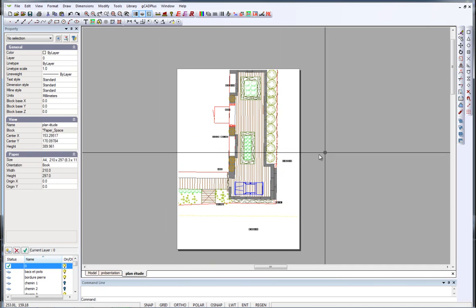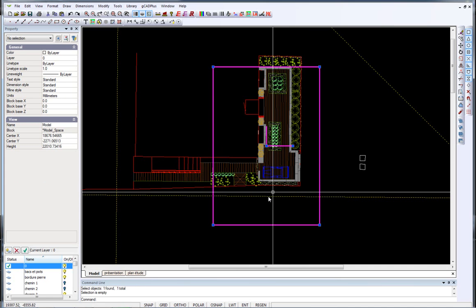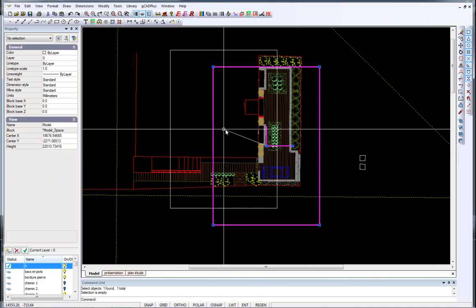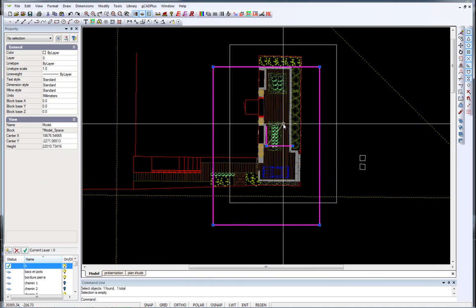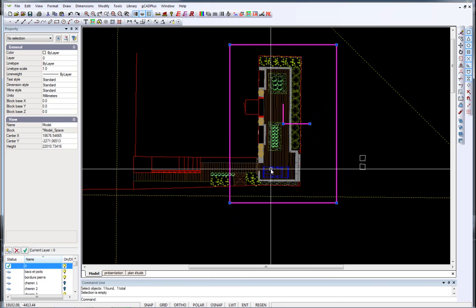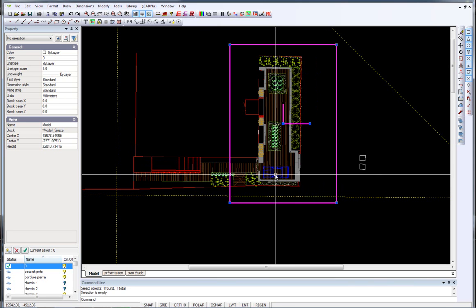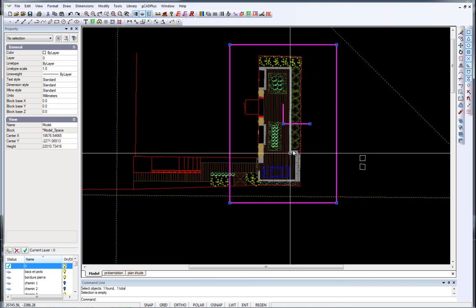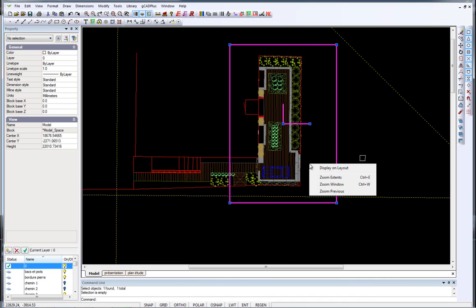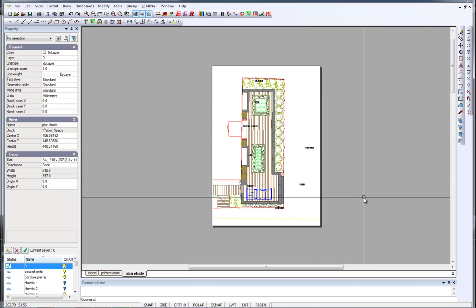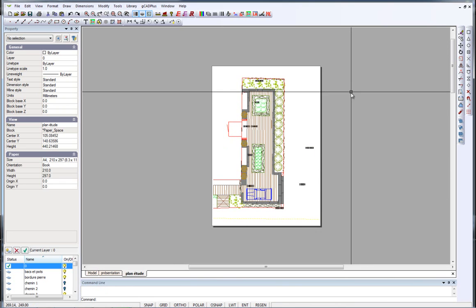What we want to show here is, as we now go to the plan view, you can see there's the layout. I'll double click in here and just reposition my layout box to sit over. We won't take the whole site here. This is just in fact the rear of the house. So presumably entrance is through here to a parking area, and so we're now displaying the whole design. So now display on the layout, right click and deactivate the viewport, and it sits there.